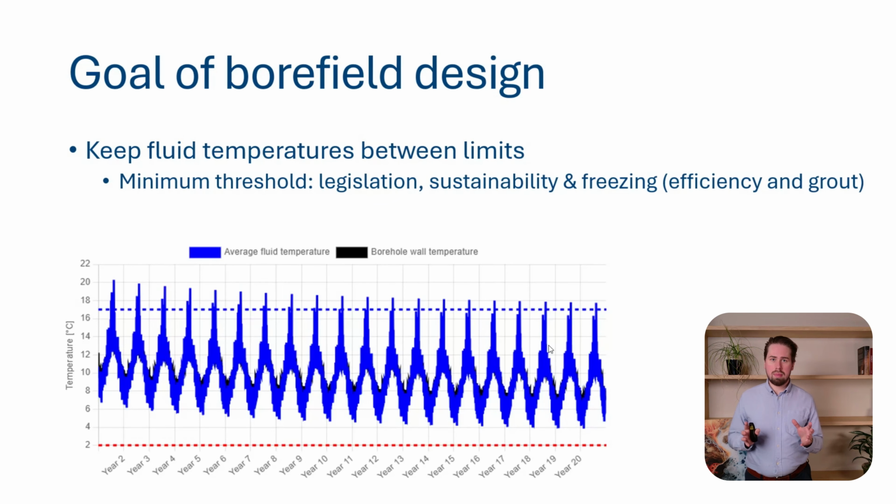So when we talk about borefield design, we're talking about temperatures. Now, the rest of this course will be about these temperature plots, so don't be afraid if not everything is clear at the moment. But in fact, what you see here is a temperature profile, temperature on the y-axis and time periods on the x-axis. And what you see, it varies from season to season. So in summer the temperature rises because you're injecting heat in the ground, and then in the winter it cools down because you're getting the energy out of it. And this blue line is the fluid temperature circulating through your borefield.